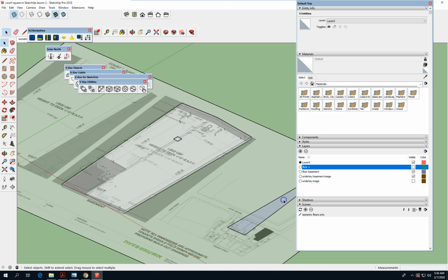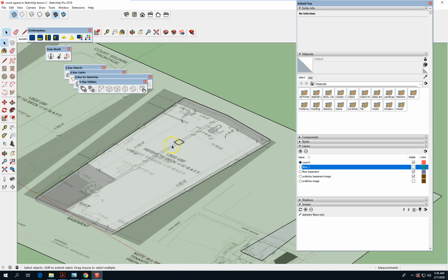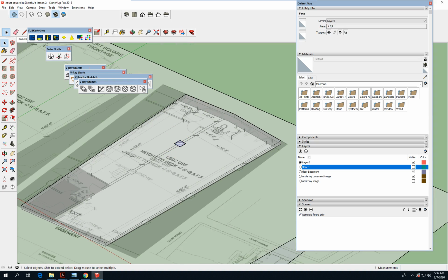Oh, we don't need this anymore. Well, we'll leave it there for now. We're gonna push this 11 feet 8. Why am I using 11/8 and not 10/8 to go to the underside of the floor above? Because it's easy to remember, and it's written down as an annotation there.